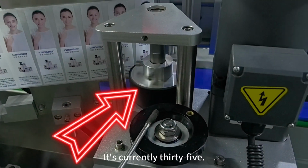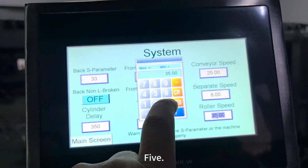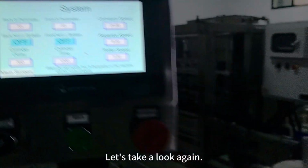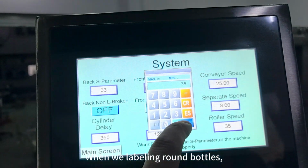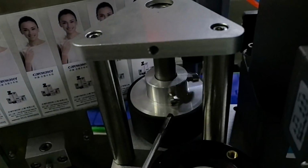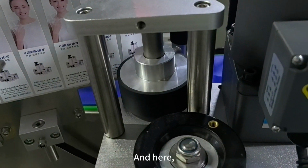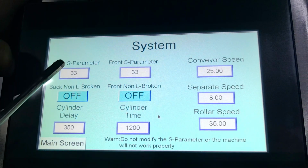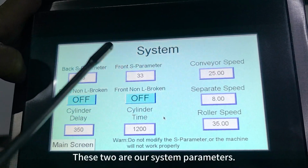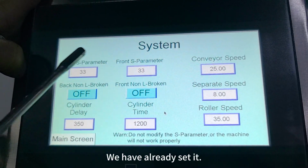It's currently 35. Let's set it to 5. Let's take a look again. This is very slow. When we label round bottles, the roller's speed needs to match the label speed. And here, there are back parameter and front parameter. These two are our system parameters. We don't need to set them. We've already set them.